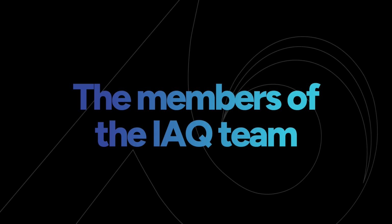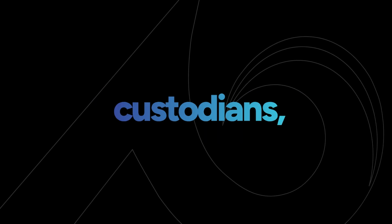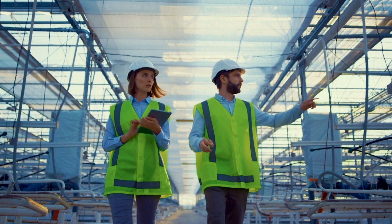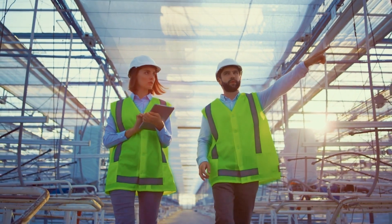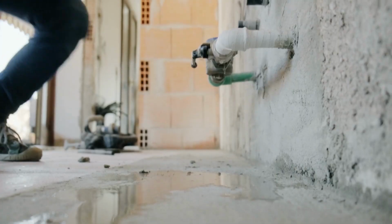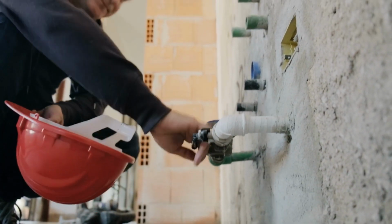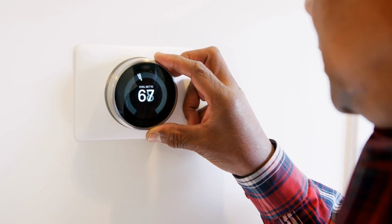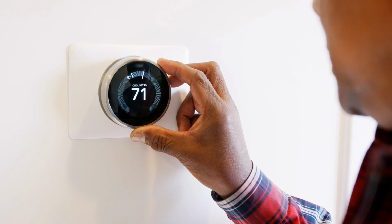The members of the IAQ team should include employees, administrators, custodians, and any other pertinent staff interested in being on the team. One task the IAQ team is responsible for is identifying and assessing air quality issues. This includes regularly checking for leaks and drying any damp areas within 24 to 48 hours. The team needs to also verify that the temperature stays between 68 and 78 degrees with a relative humidity of